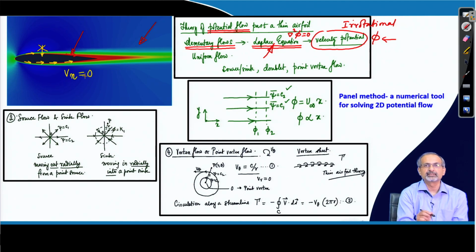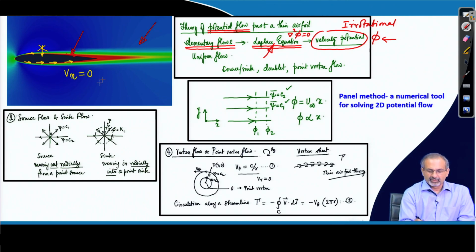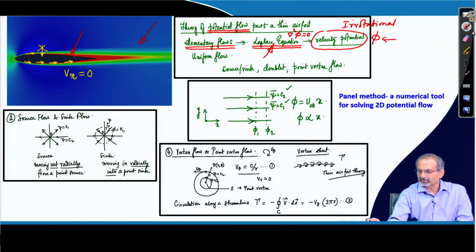So, this is precisely the boundary condition that you have to apply for any kind of inviscid flows that you are modeling. That is true for potential flow modeling as well as inviscid flow modeling using the Euler equation, for example. Additionally, in potential flow, you have the presence of a velocity potential. So, what you end up solving is essentially phi at the end of the exercise.